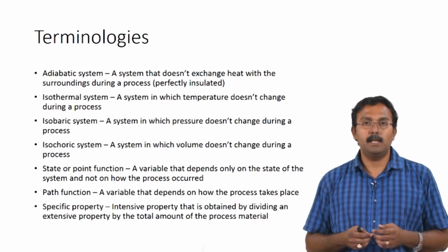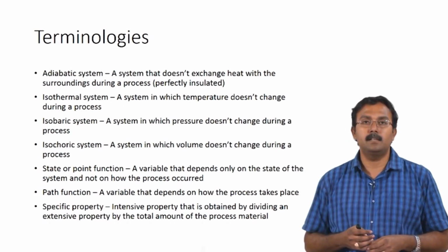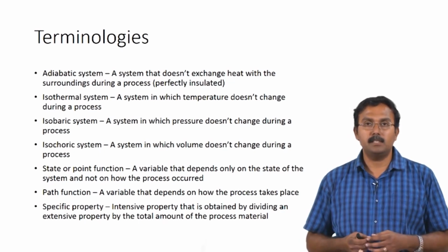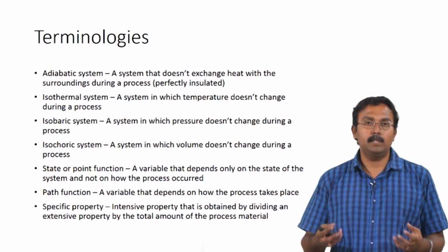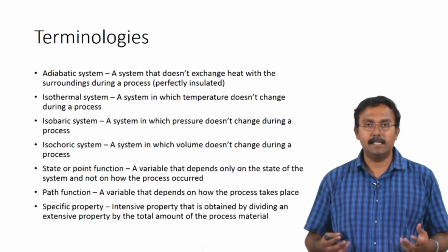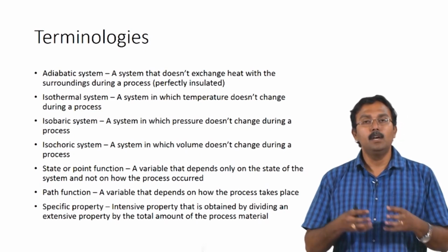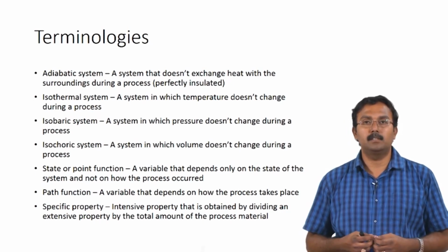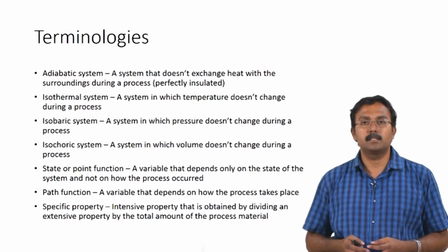So, when we use the steam table, you would see the specific volume, specific internal energy and specific enthalpy listed, and this is possible because it is not dependent on the size of the system, and it is only given as a specific property. We can take these values and apply them while we perform calculations for systems of any size. And when we multiply the mass or number of moles of the component by the specific property, we get the total value for these components. So, this is really useful while we perform calculations.